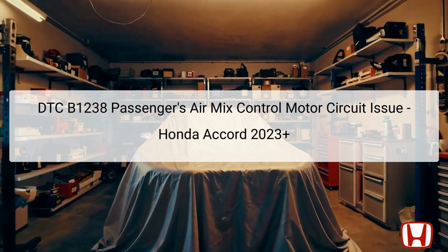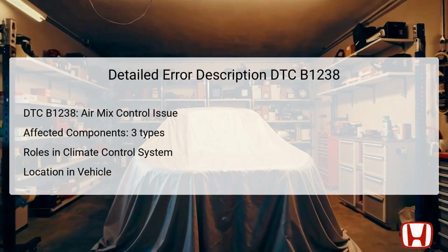Proper diagnosis is essential to pinpointing the issue, ensuring that either the air mix control motor, its associated circuits, or the climate control unit requires attention. DTC B1238 signifies an identifiable malfunction in the passenger's air mix control motor, its associated linkage, or the door mechanism. The passenger's air mix control motor regulates the airflow temperature by adjusting the air mix, directly influencing the cabin comfort levels. The linkage connects the motor to the door, which physically controls the airflow. All of these components are usually located behind the dashboard around the climate control unit.